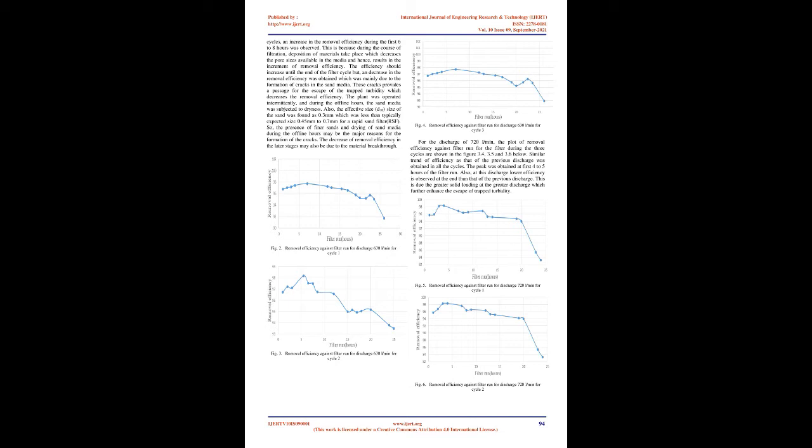It is important for the removal of impurities like iron and dissolved gases like ammonia which are present in the source water. During the aeration process, scrubbing action and oxidation takes place. Scrubbing is caused by turbulence created which removes the dissolved gases from water. Oxidation is the process in which the impurities like iron and manganese are oxidized to form precipitates. These precipitates remain suspended in the water and can be removed through other processes in the treatment like filtration.